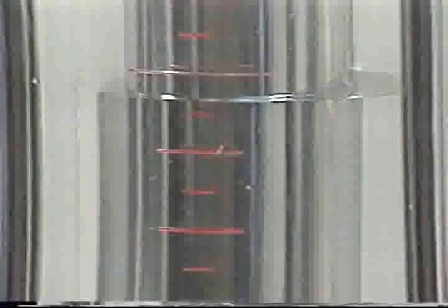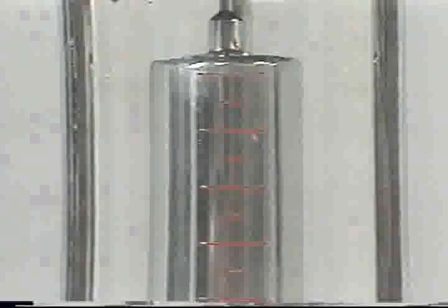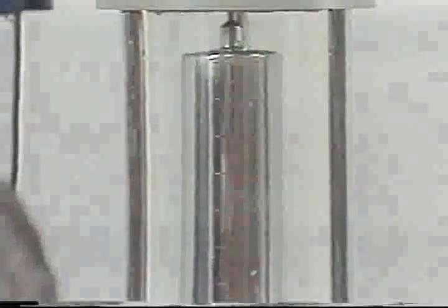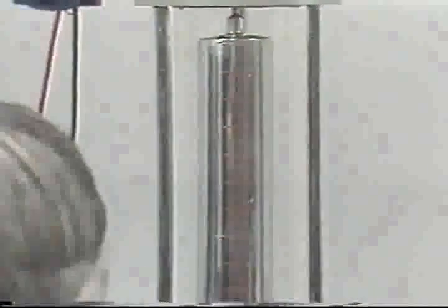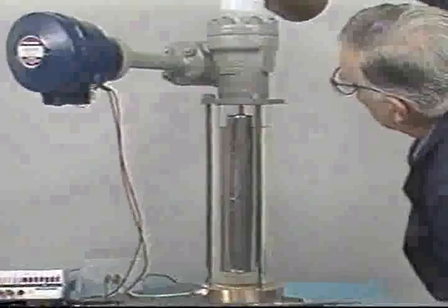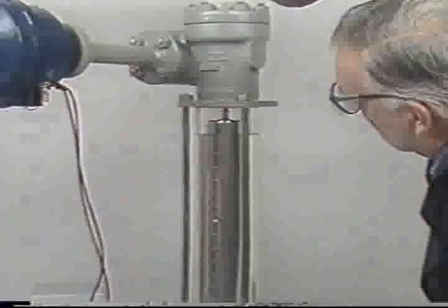The movement of the displacer is translated to a torque tube, which converts the movement to a 4 to 20 milliamp instrument signal. The spring action of a torque tube is nonlinear. Nonlinearity, then, is not an error that's adjustable for this instrument. However, the friction inherent in the mechanical movement of the displacer and torque tube can result in other errors like hysteresis.